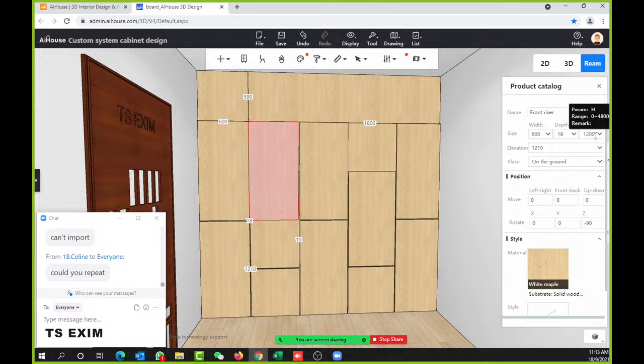The height I make it 580 as we calculated already, and this distance I'll make it 0. And this one the 600, I make it 0. Complete. So remember, copy, then change the height first, then you change the distance. Like a puzzle. Okay, so I'll give you 1 minute.